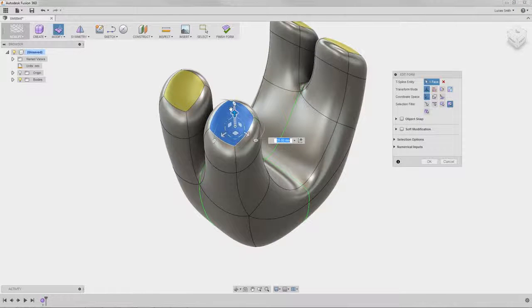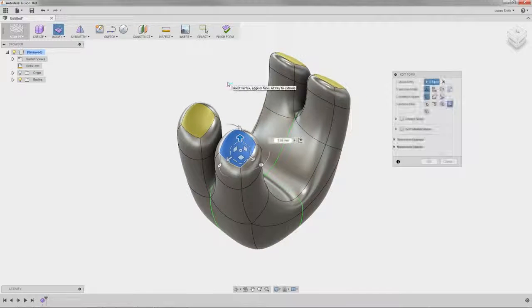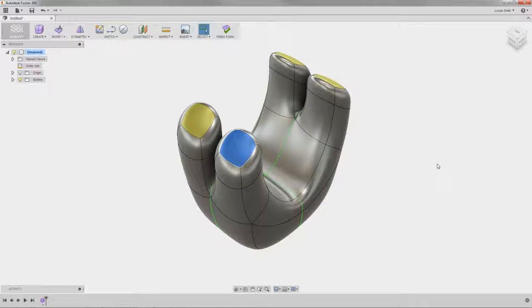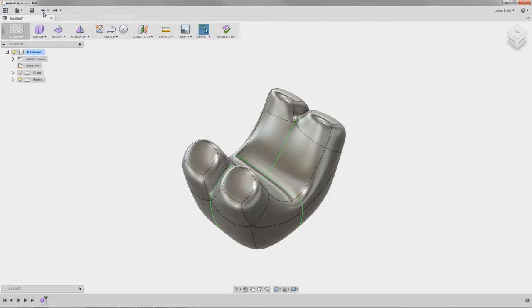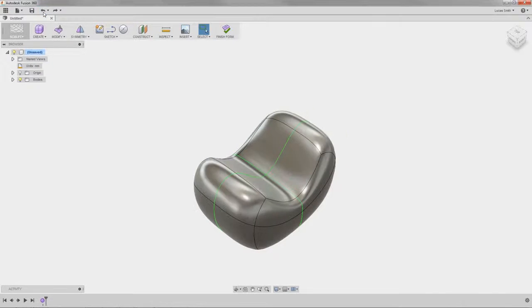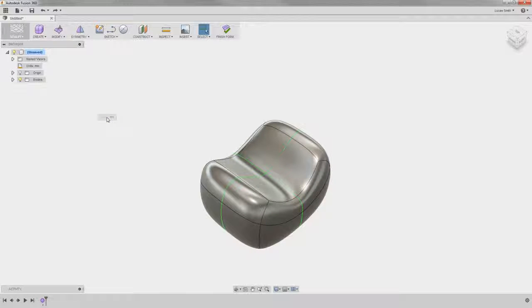depressed. Fusion 360's Sculpt environment has another useful feature: nearly unlimited undo capabilities. This allows you to return your shapes to previous states quickly and easily. Watch as I click the undo icon, and you'll see that each edit made to the shape is undone step by step. I can also quickly do this through the marking menu by right-clicking and swiping to the left or 9 o'clock position. Keep in mind that at any time in the design process, you can exit or re-enter the